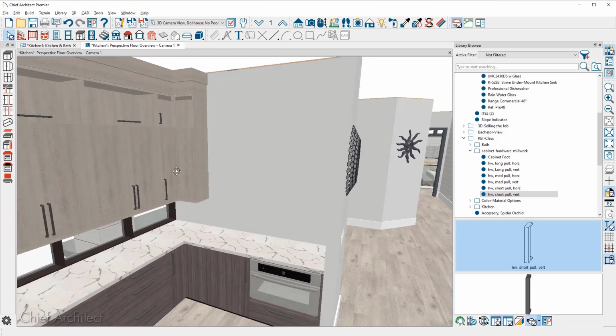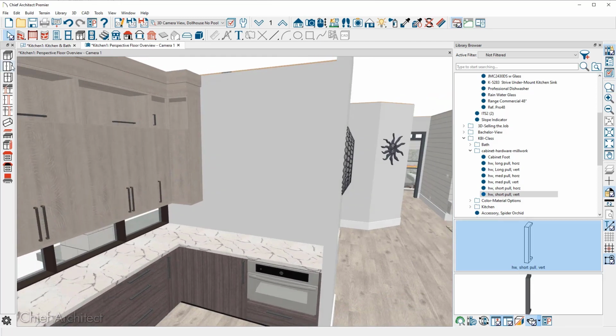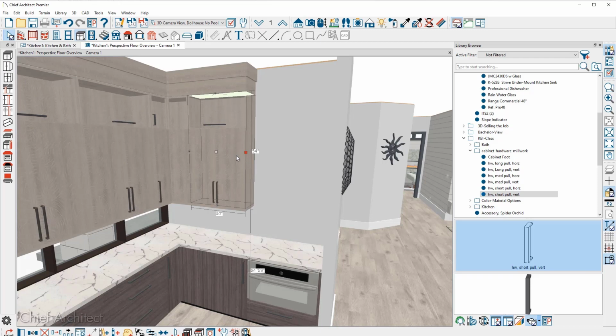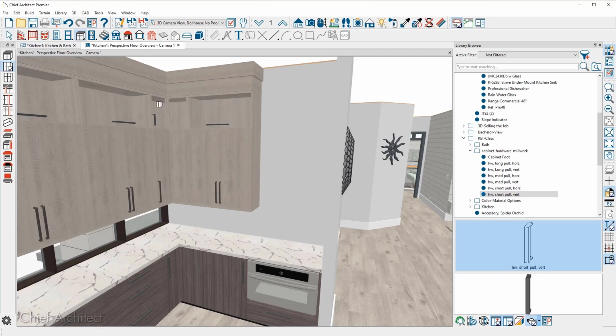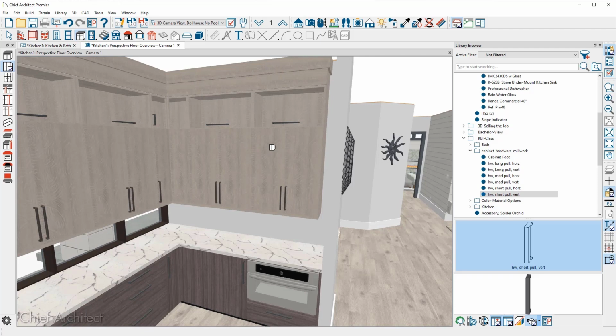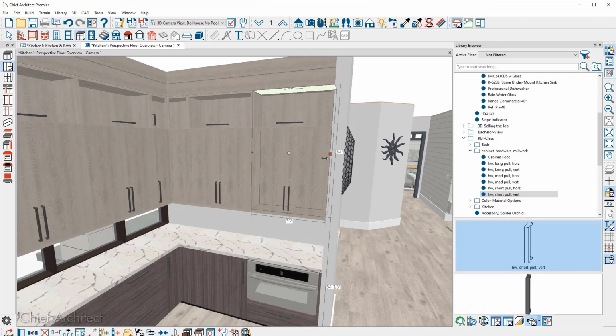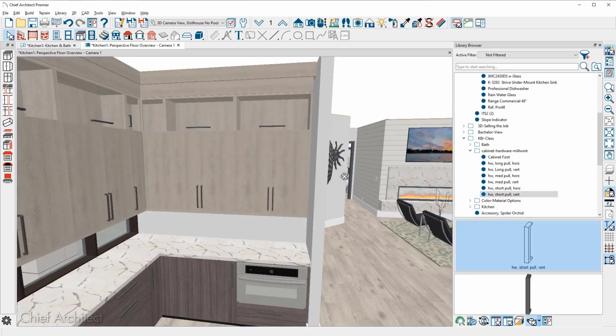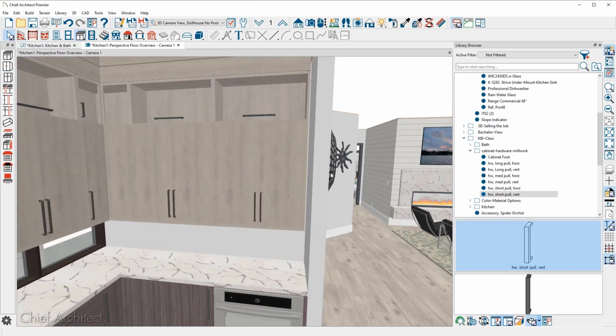Rotate around a little bit. Grab our wall cabinet tool. Place another wall cabinet off to the side. Press the spacebar to get out of that cabinet mode. Click on the cabinet. I'm going to resize it to 33 inches. And I'll just repeat the process. You can either make a copy of that cabinet or place an entirely new cabinet. And then after it's placed, grab the handle, slide it over. You can do this in an elevation view, in a floor plan view, or in a perspective view that I'm doing it in here. Notice that we have the same type of gap in there.